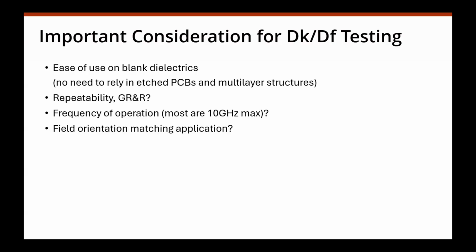Another thing is the frequency of operation: is the frequency you test your Dk and Df at somewhere close to where the application works? If not, it may not be applicable. And I've talked about the field orientation already. Of course, that should match your application.